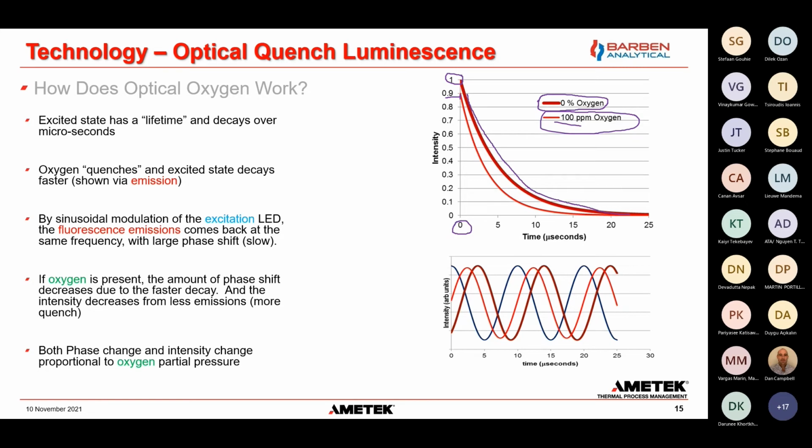Okay, so that becomes important for us because people did make the measurement off of this difference, the intensity difference, for many years. But the problem is putting that into the field becomes problematic because we would have to know exactly the output from the LED, and also the fiber optic cable. If it moves, the light intensity could shift as we lose a little bit of efficiency in the fiber optic. There would be lots of different perturbations that could affect this differential.